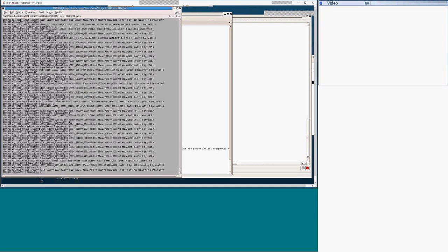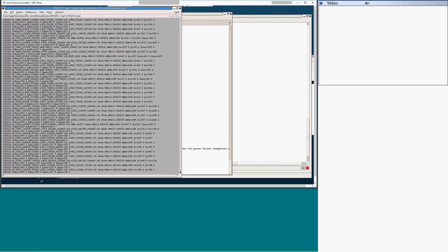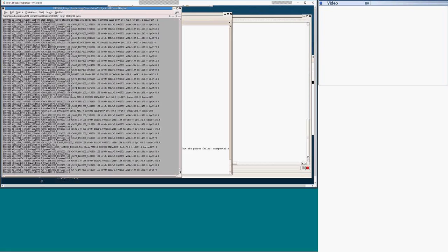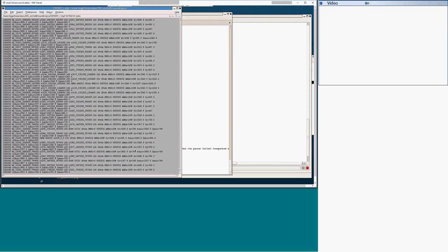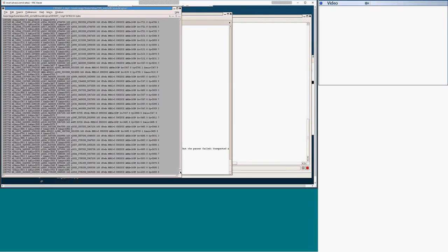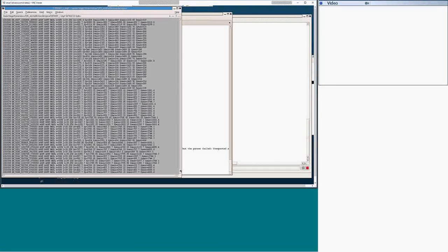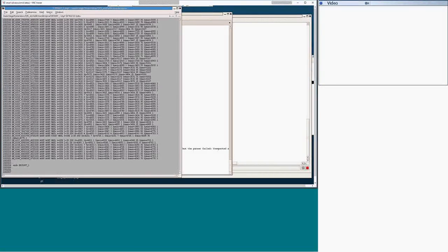diodes. And the way I was checking what Michel was extracting, he was removing extraction of diodes in his configuration file. I do not know how correct that is, because in the next extraction diodes were back in the circuit. So again, this is what you need to decide, because these are parasitic diodes as far as I understand. This is what you need to decide, because I don't know what your circuit is.